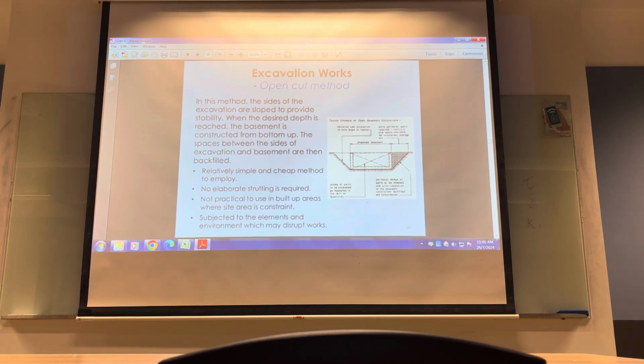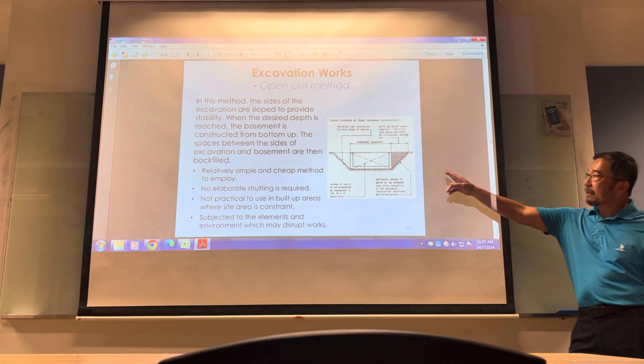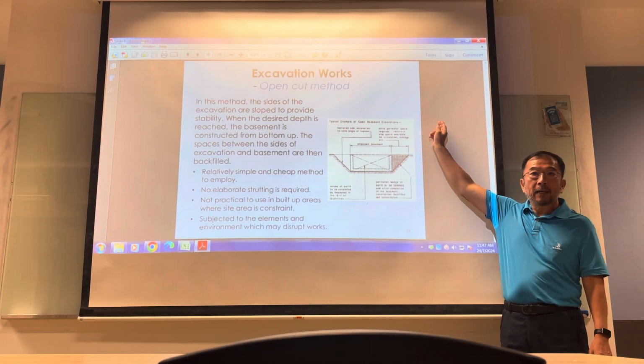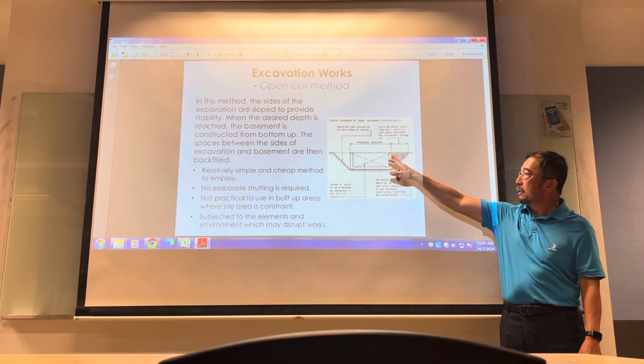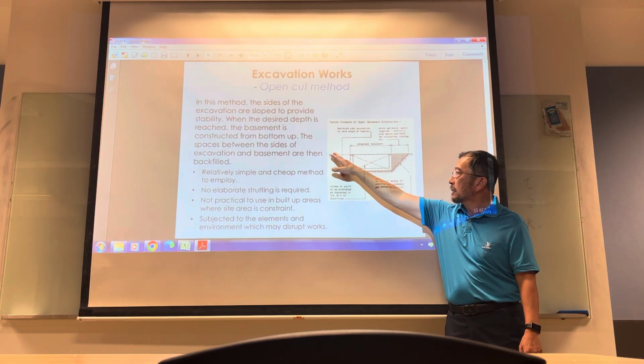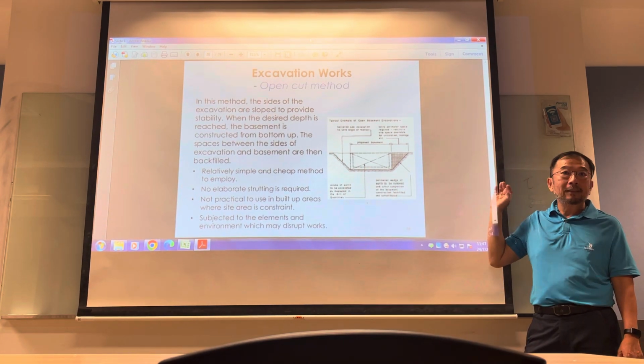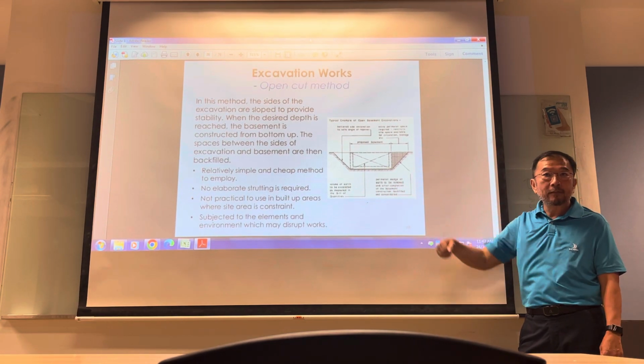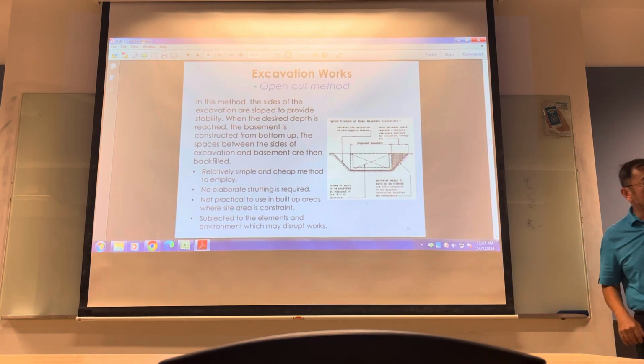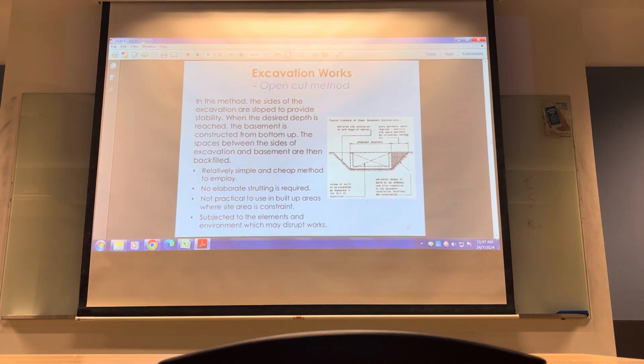Open cut, cheap, good if you have area, if you have less disturbance, less restriction. But don't forget, whatever you excavated out, you need to backfill. So this portion outside of your structure become additional soil that you need to excavate, additional soil that you need to backfill after your structure has been completed. So you need to cater for that in terms of time and cost.